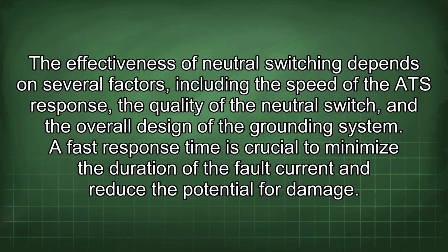The effectiveness of neutral switching depends on several factors, including the speed of the ATS response, the quality of the neutral switch, and the overall design of the grounding system. A fast response time is crucial to minimize the duration of the fault current and reduce the potential for damage.